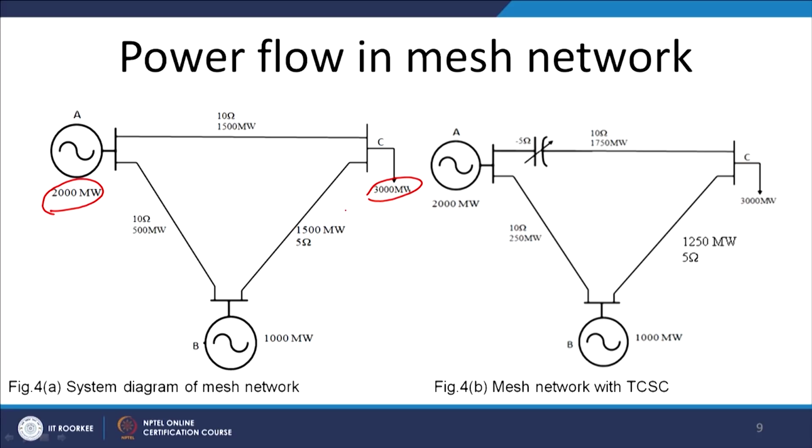Unfortunately, since this line AC cannot take that amount of power, the power required has to be wheeled through the networks AB and AC. Now in a power system where there are different stakeholders and networks owned by different people, this line AB may be owned by another distributor network, and they may charge for carrying current through this network. If a smaller amount of current is carried, then less tariff will be there, and thus power available to the consumer will be costlier.